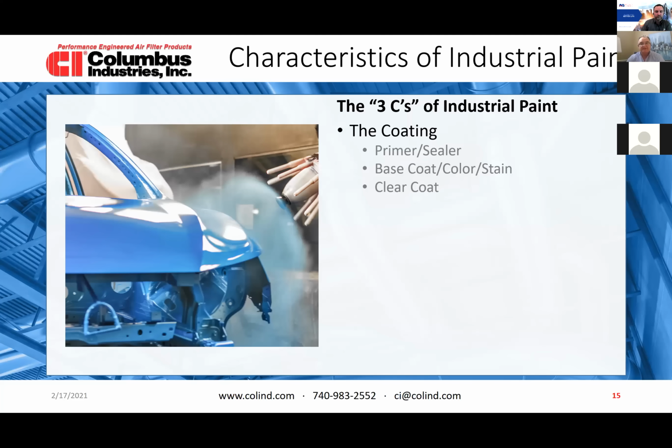The primer is also called a sealer, especially in the wood industry. It's basically to seal any porous surfaces to stop them from absorbing the second coat, and also to protect from corrosion and so on. The clear coat is the coating that's used to protect from the elements, heat, rain, sun, and also to give it a certain aesthetic aspect.